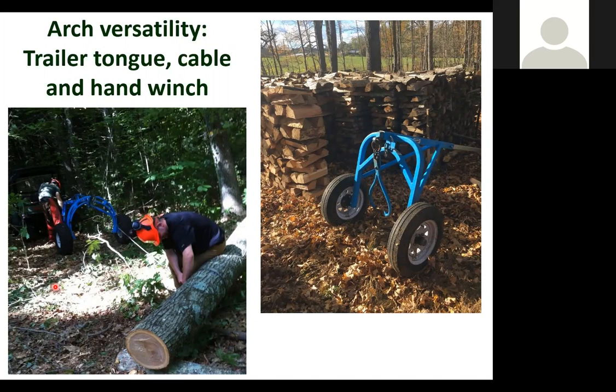And you see in these photographs a capability where we have a trailer tongue, and this is attached to a standard trailer hitch on the back of the RTV. And then there's a hand crank winch with a cable. The young man is setting a choker with a cable and a hand winch, and will be able to winch the log into where the arch is.